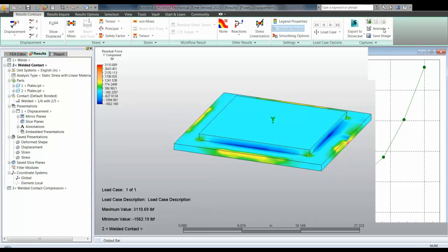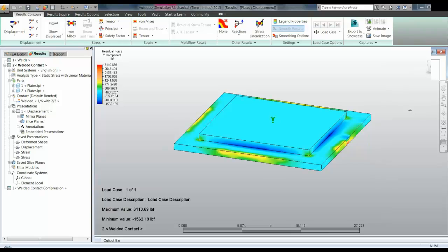Okay, when I perform a weld analysis, I would run a simulation to connect the nodes at the location of the weld, and select these nodes in the area of highest values, obtain the force per inch, and then refer to the AWS welding code to see if this was acceptable. Actually, that does make quite a lot of sense, and our example, which is still vaguely displayed in the background of making a path plot, not only allows you to identify what the local force per inch is, or load per distance, but see what that magnitude is, and the chain is as strong as its weakest link, so that would make appropriate sense.